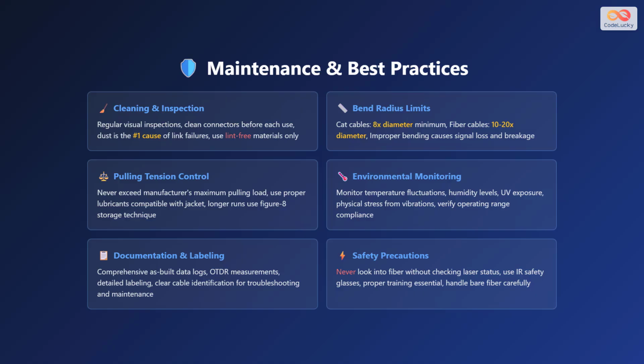Finally, follow proper safety procedures. Never look into fiber optic connections without confirming laser status is off. Always use infrared safety glasses when required, and obtain proper training before handling sensitive fiber optics.